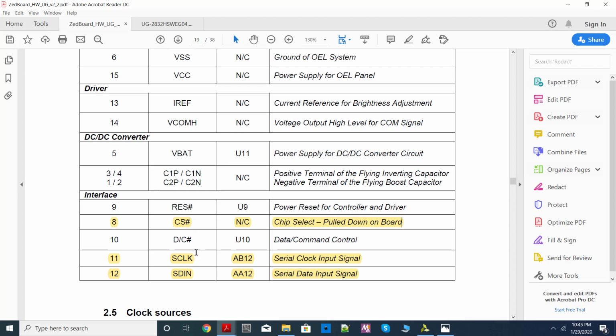Now here you can see only 3 wires. So this is the clock signal. This SDIN is the same as MOSI, master out slave in, and this is the wire through which the FPGA will be sending data to OLED. There is no master in slave out wire available. The Zynq chip will never read data from an output display. That's why that wire is missing. Now this CS, and this hash stands for an active low signal. That means the signal should be low for activating it. This signal is the same as slave select.